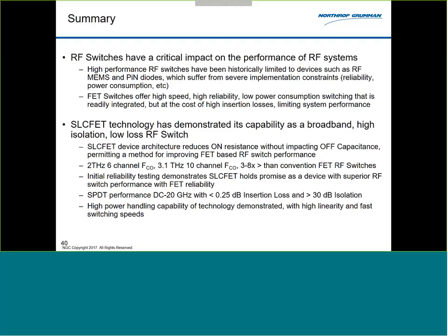So with our current baseline, the question is, what is our maximum off-state voltage, maximum on-state current? The device as we've built it right now has a breakdown voltage. Our baseline architecture has a breakdown voltage of 40 volts. From an RF perspective, that's pretty decent.